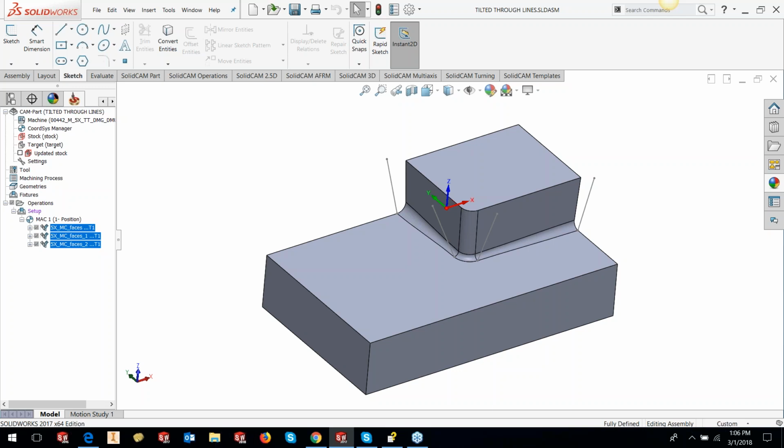And then we are going to focus ourselves on gouge check, how to avoid gouges using the gouge check methods, and also how to machine the part using a gouge check. Okay, there are 2 items here. We are also going to see the third topic, which is basically the priority when you apply gouge check. I have seen in many users, they apply the gouge check like they feel it's necessary, but actually you need to have your priority. You need to put the right one first, the second one next, and third one, and so on. If you jumble in that, then you get wrong results. So you need to understand the priority.